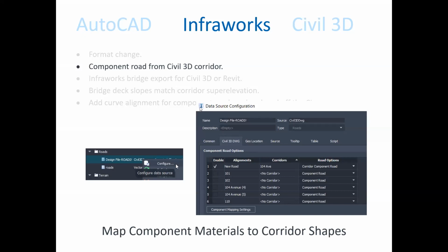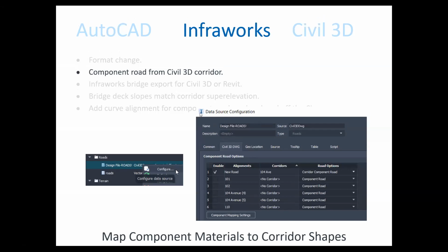Now I'll just demo this real quick. Right, just before I head into the model, the interface has changed a little bit as well, right? This is the home screen now. It's a very different home screen than you probably remember, right? And the reason they did this really was to make it a little more consistent with the other Autodesk products. Right? On the left, we have recents, open, new from Model Builder, and then we have a BIM 360 tab here as well. So the InfraWorks interface is a little bit different on the home screen.